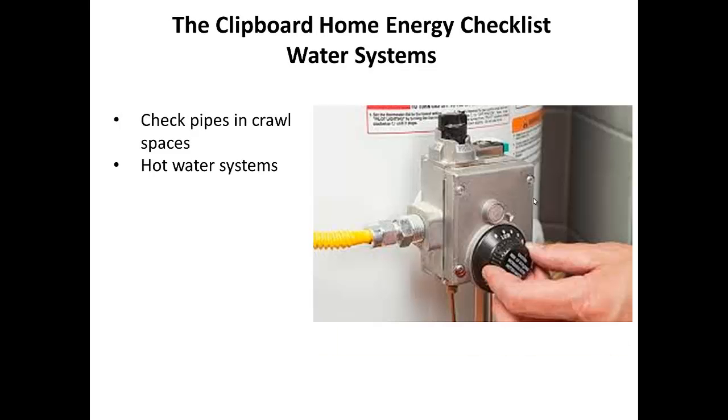For hot water systems, generally speaking, you want to set your thermostat to about 120 degrees. You have to kind of adjust it yourself and decide how warm you really need it. As cool as you can keep it and still have it warm enough, that's where you want it. I put it so it's a little bit too hot for me to have my hands just sitting underneath it, but it's not going to scald me. And you're talking about your tank losses here from the surface of this tank.